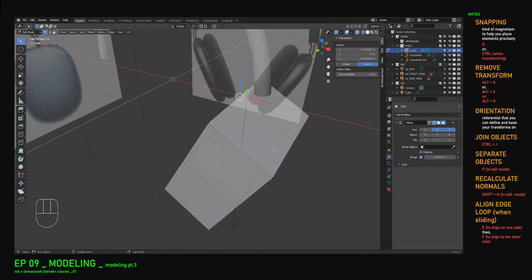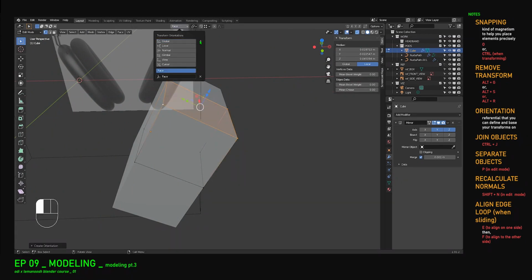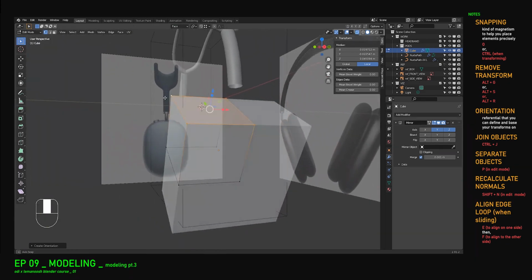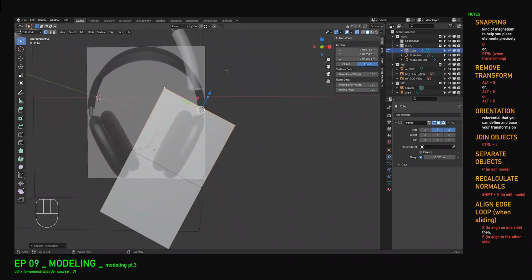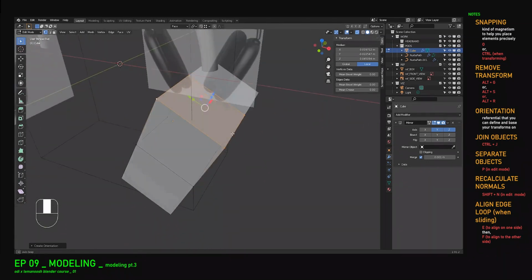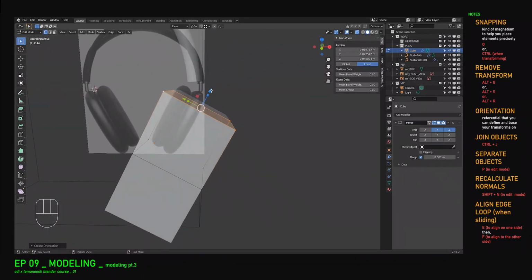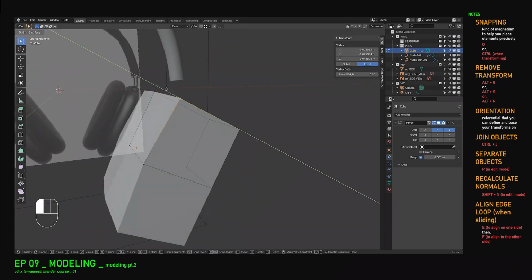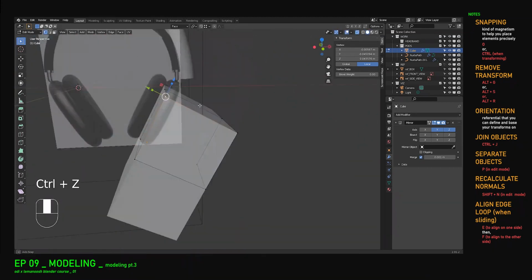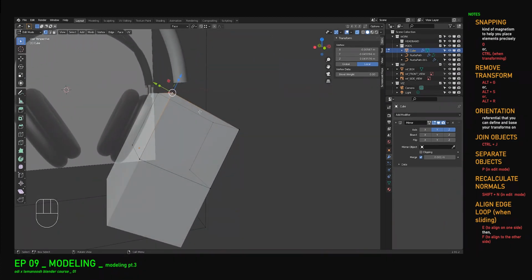But so to create our orientation, let's select a face and press plus, and basically it will take our face and get the perpendicular axis and then the 2 axes that are defining the rest of the face. So this is exactly what we need, because then we can just push things up and down, as well as move points there, and this without actually having to follow the lines and everything.